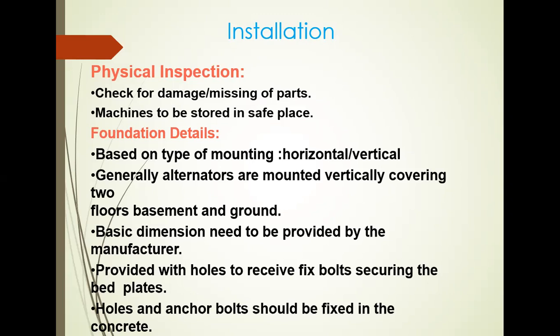Okay, that is specification of the machine. We can mount or install the machine accordingly. The basic dimension needs to be provided by the manufacturer. So it is provided with holes to receive fixed bolts securing the bed plates. Holes and anchor bolts should be fixed in the concrete.